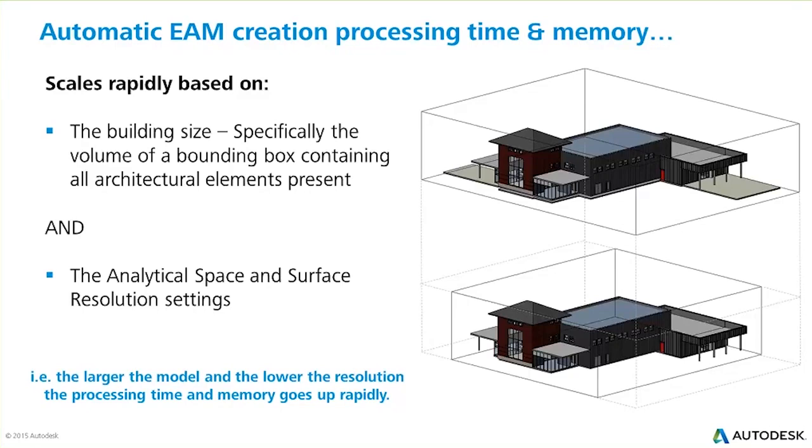If you're going to do this for the first time, I would recommend don't do it on your biggest, fattest Revit model for the first time. It's just going to take you longer to learn how this thing actually behaves. Do it a few times with some smaller models, and then you'll understand how, for example, excluding those floor plates which are making the box bigger than it needs to be, and they really don't matter for the energy analysis. It's simply taking longer than it needs to be.